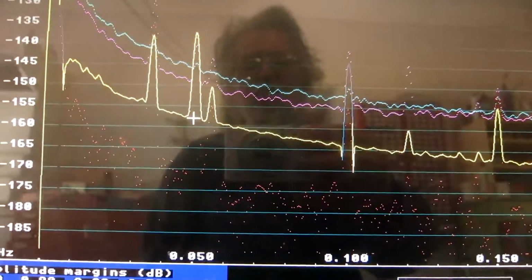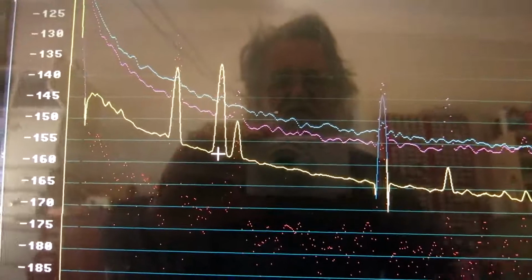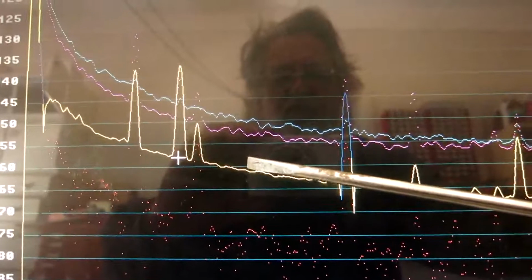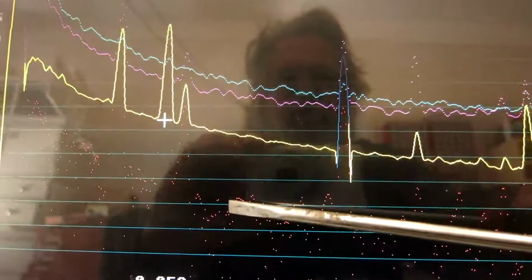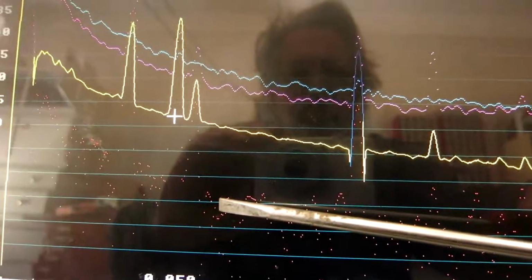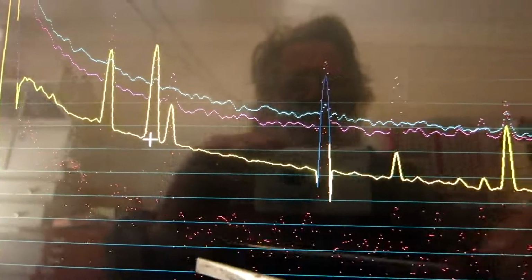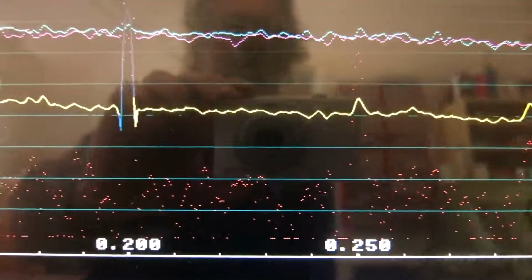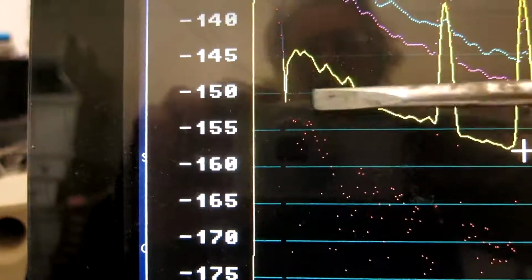222,000 averages. I now have a stable spectrum with fairly small fluctuations due to noise, and I can see the separation between the noise from the test object, the real part, which is positive here, and the imaginary part of the correlation spectrum. This separation is very large, so I have good data, and that's so all the way up to 200 Hz. But at very low frequencies there is a problem here.